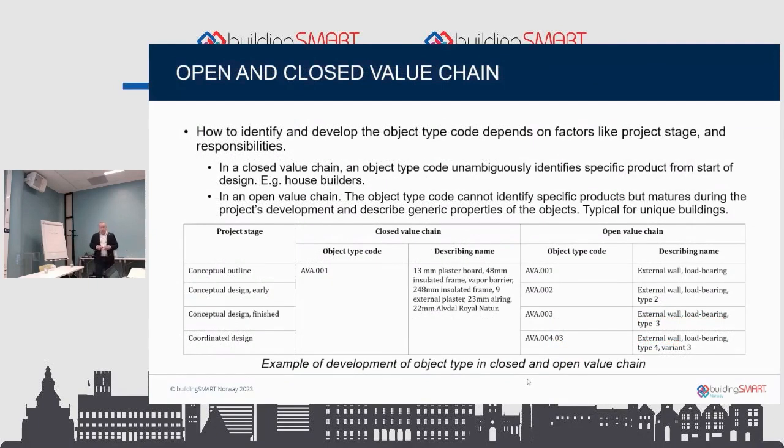We also identify, when you are identifying products, let's say, for example, we always talk about walls. Walls are actually not the best example, but in this case, walls are good because they're actually composites, and they consist of very many products. In this case, I have an external wall. It's cladded with some wood on the outside. It has a plasterboard on the inside, and then it's insulated and has vapor barrier and so on.